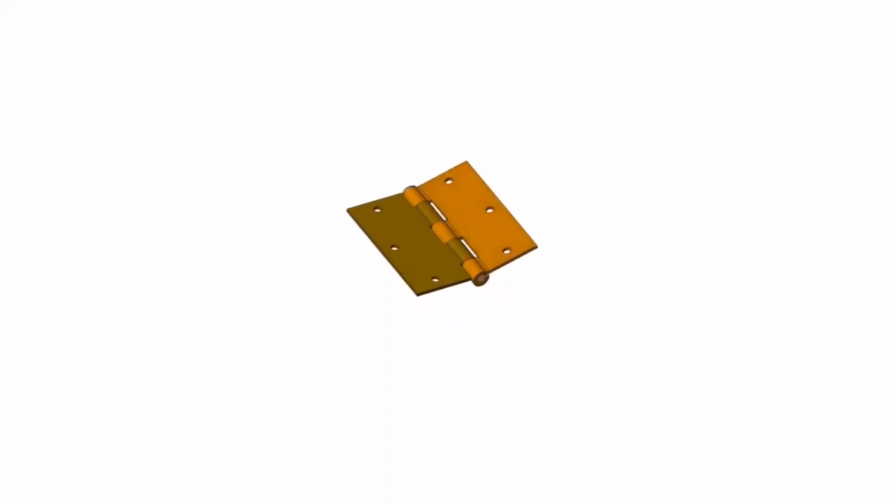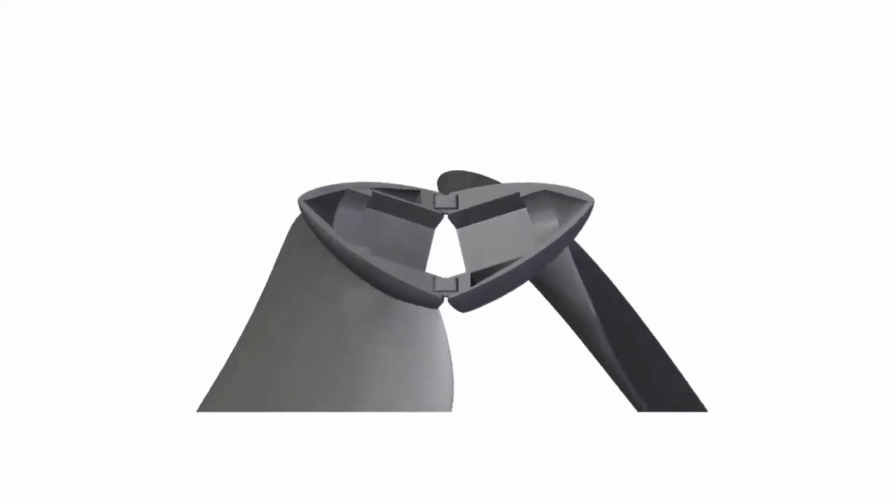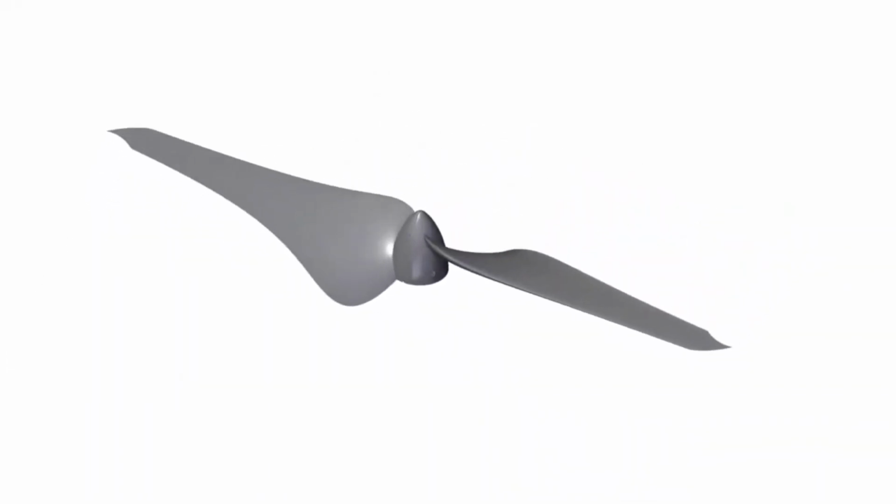Originally, the hinge was going to be a butt-style hinge, like that seen on most doors. However, we felt that since this type of hinge only has rotational freedom of movement, we would not have enough tolerance in the printing process to ensure a good join between the two halves. Therefore, a sliding block mechanism was designed, giving us the right amount of freedom of movement in all three axes.